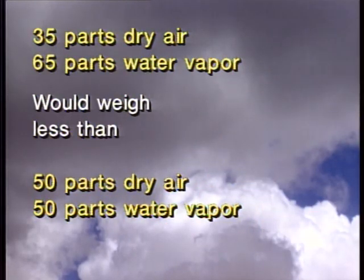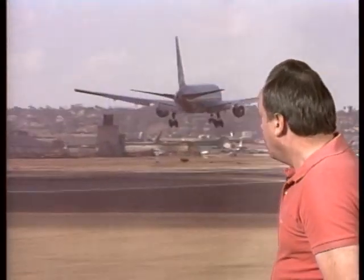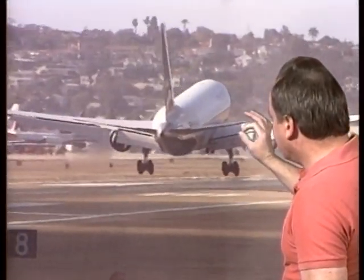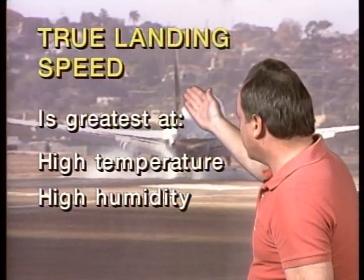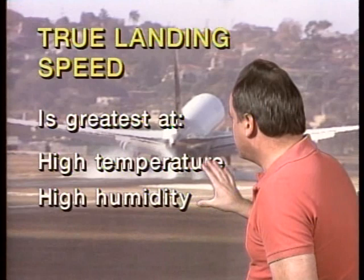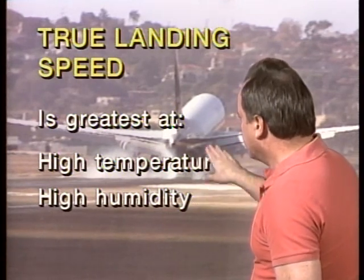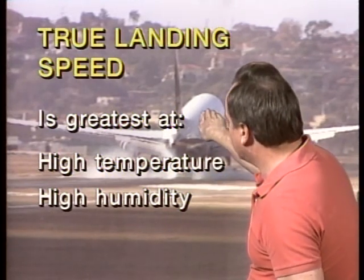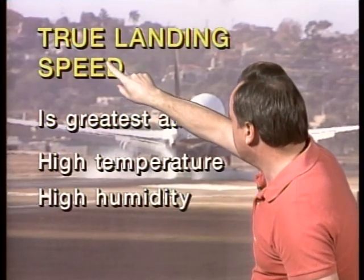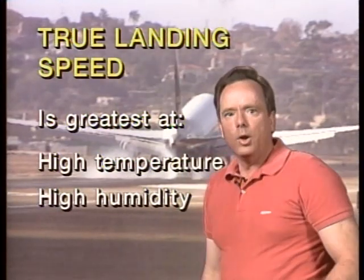All right, now they're also going to ask you what is the effect of high temperature and high humidity on the landing speed of an aircraft given the same indicated airspeed on final. And the answer is the true landing speed of an aircraft is greatest at higher temperatures and higher humidities because the air is less dense. So even if you're flying at the same indicated airspeed on landing, if you increase the temperature and increase the humidity, the true speed through the air will be higher.